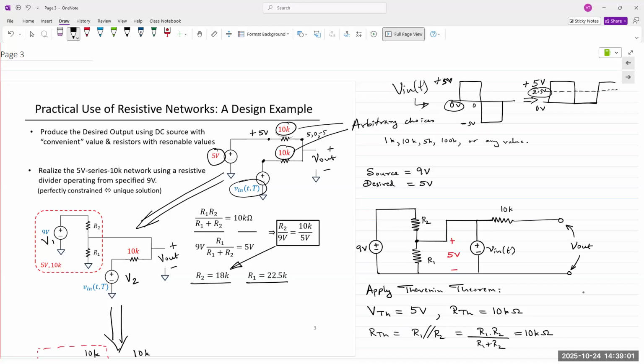Yes. Sure. Yes, that is correct. So it's related to the same point that was brought up earlier. So the question being asked is, would we expect this kind of circuit to go, instead of going from -5 to +5 and shifting it from 0 to 10, is it because of the resistors? The answer is yes, because of the resistors.